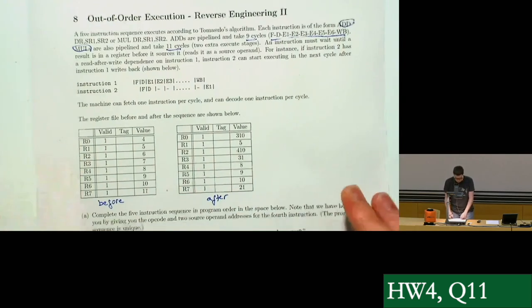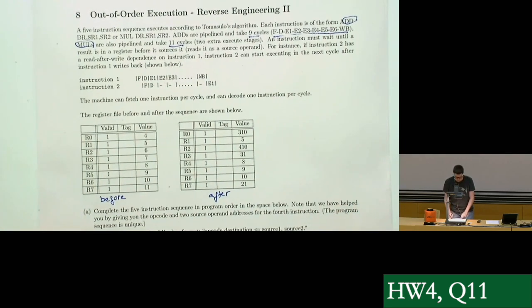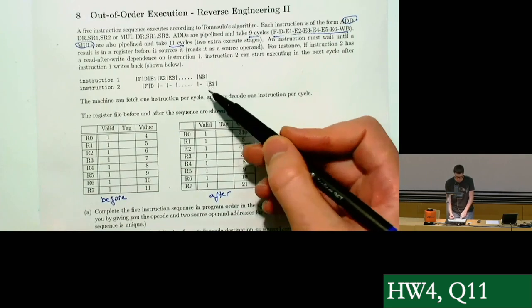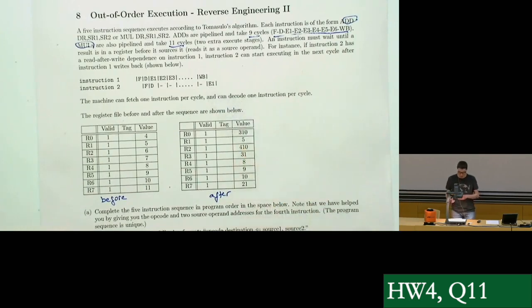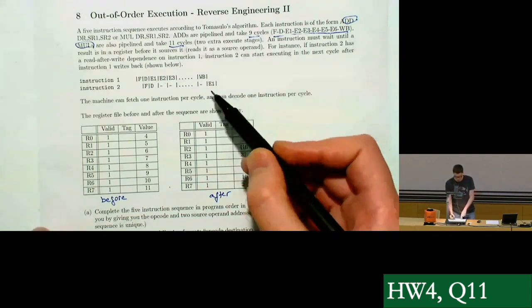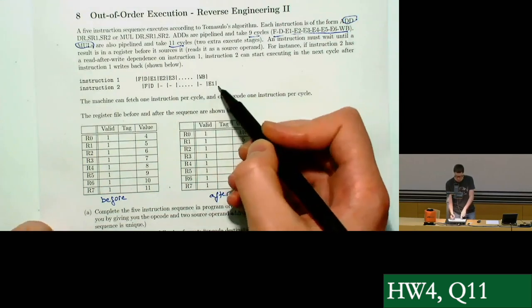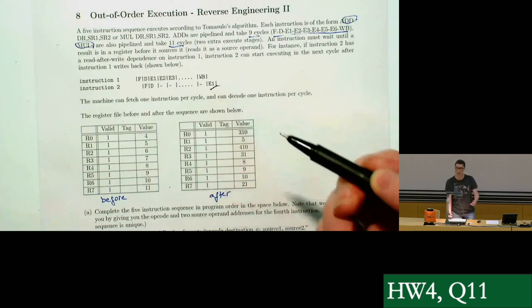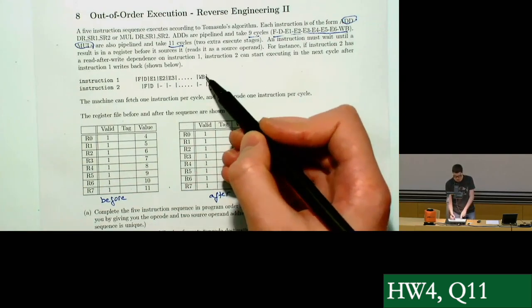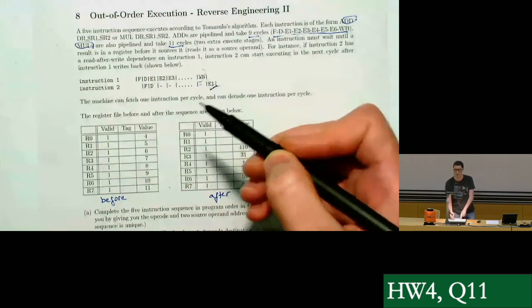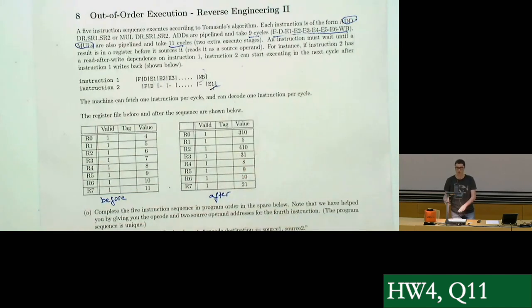And the question is also describing well what the policy is for reading back the data. Basically, when you have a data dependence between 2 instructions, the instruction that depends on the result of the previous instruction has to wait for the data to be written in the write back stage, and in the next cycle it can start executing.